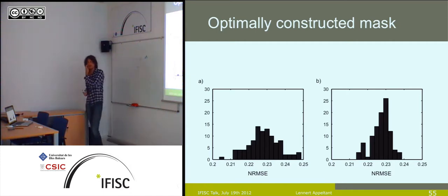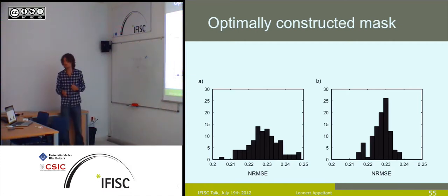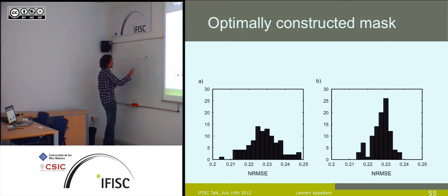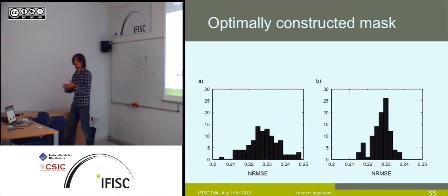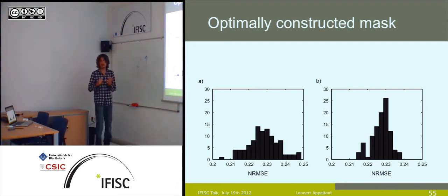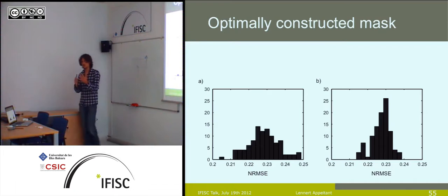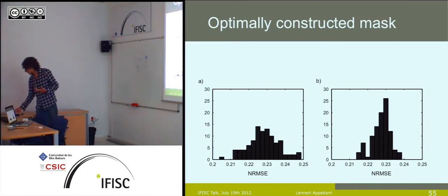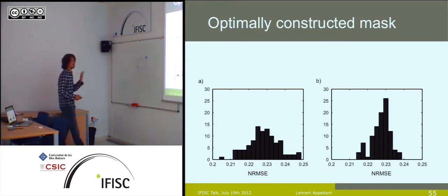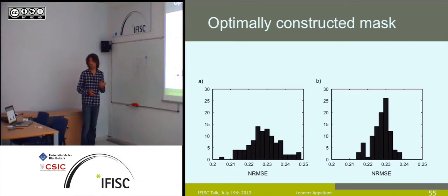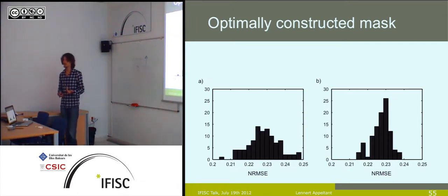And using a technique that comes from maximum length sequences, what we do is, given a certain sequence length of importance, we try to create maximum variability in these states. Not only does this allow us to make our masks as short as possible, and a shorter mask means less virtual nodes, means a shorter tau, so we are processing faster. Also, we create the maximum variability in the reservoir states that we generate in our delayed feedback reservoir.